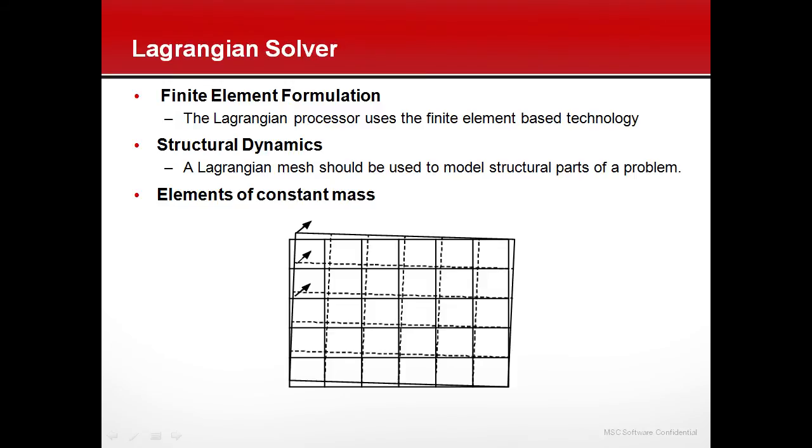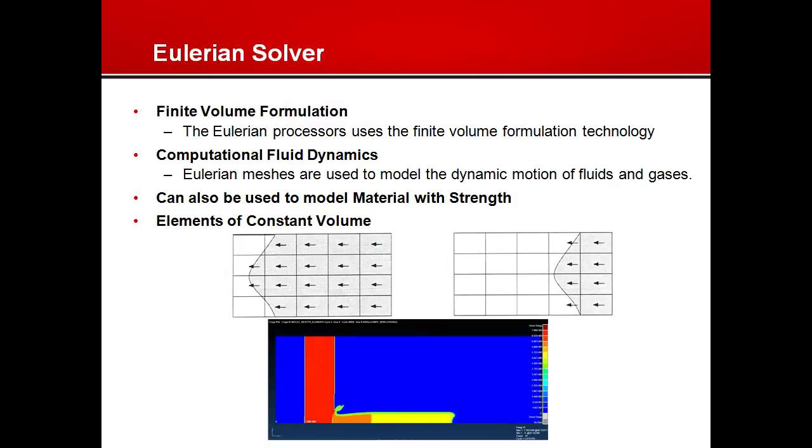Very similar again. Now, conversely, an alternate technology is the Eulerian solver, which is also typically part of the explicit solvers. At the bottom there is an example of this. This is a stationary mesh. It happens to be a very fine mesh, so I don't show it, but you'll find that the elements don't move. What's moving is the material from element to element. Essentially it's a fluids problem. So we apply initial conditions. It's a bullet hitting a flat plate. We define what the materials are and where, and in this case the bullet has a velocity and gets projected towards this plate.